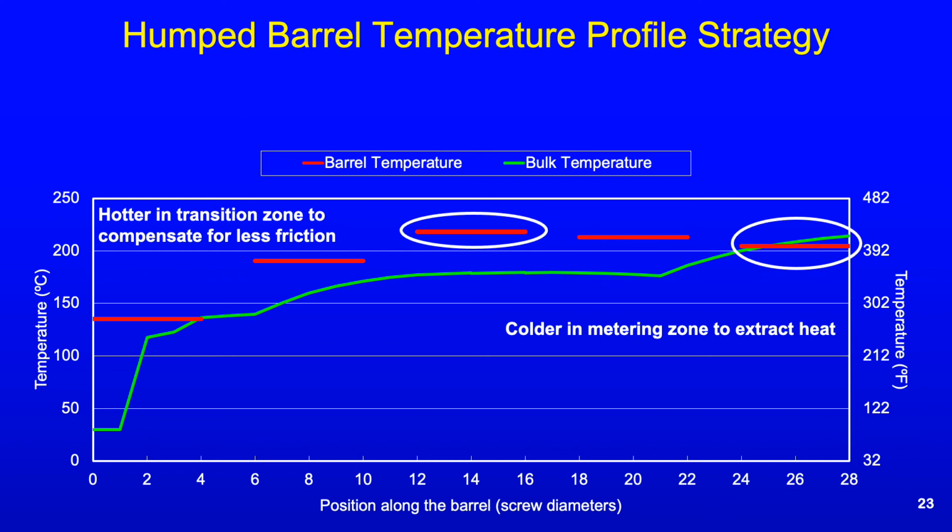We always typically keep the last zone of the extruder slightly colder than the melt. And if you remember in the temperature profile, well, you're going to see it, they set the die temperature 10 degrees lower than the screen changer, which is not what I would do. Typically, I'll keep the temperature of everything after the extruder at whatever I think the melt temperature is.